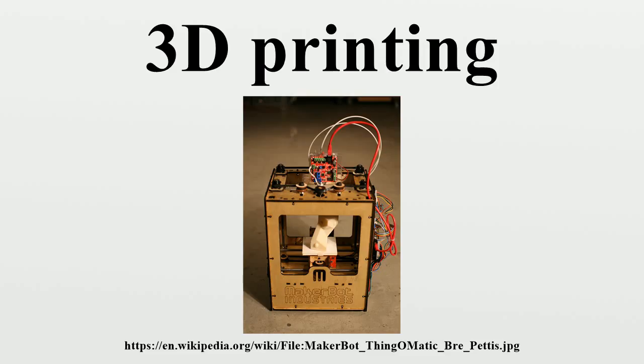In fused deposition modeling, the model or part is produced by extruding small beads of material which harden immediately to form layers. A thermoplastic filament or metal wire that is wound on a coil is unreeled to supply material to an extrusion nozzle head. The nozzle head heats the material and turns the flow on and off.